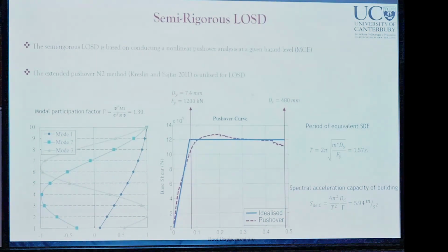For the pushover analysis, we have recommended using the extended N2 method, which has been developed by Professor Pfeiffer and his team. We have recommended this procedure simply because it has been extensively verified. It has been developed through several years of research by Professor Pfeiffer's team, but any other pushover analysis method can also be utilized in this framework.